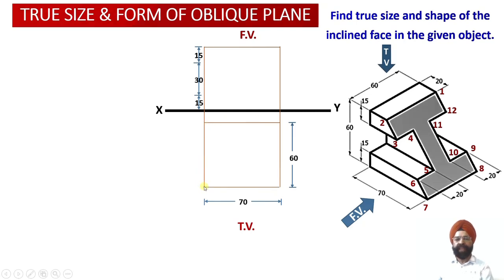Having obtained the rectangular face corresponding to the front view over here and the rectangular face corresponding to the top view construction of the solid, now we are going to locate different elements of the solid within this front view face as well as the top view face over here. Now as we have discussed, in the case of this particular solid, as we are going to look from this end, we find that the height of the solid is equal to 60 millimeter, while the width is equal to 70 millimeter.